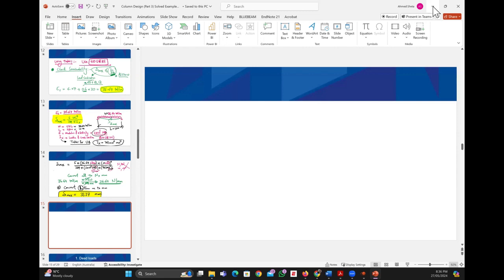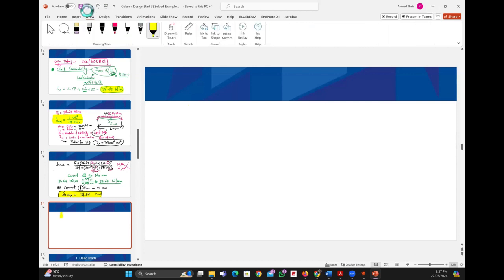Anyway, do you have any question up to now? You can ask, no problem. We still have time. What is the next step after we got the deflection? We need to compare delta max with what? With the limit L over 300. How much is L again? It's 10 meters.